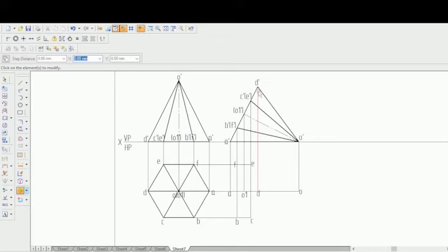Next, directly see which is the outermost point. The outermost point is actually A. So A is the outermost point, or you can also say O dash is sometimes the outermost point. So the lines that are coming from those points will actually be made hidden. So you can just see which are the lines coming from that particular point. Let's try to consider O as the outermost point. So O or A mostly both are outermost points only. So let's say O is the outermost point.